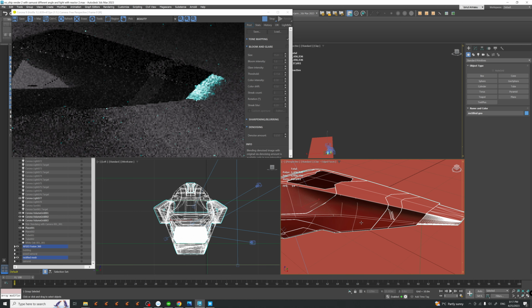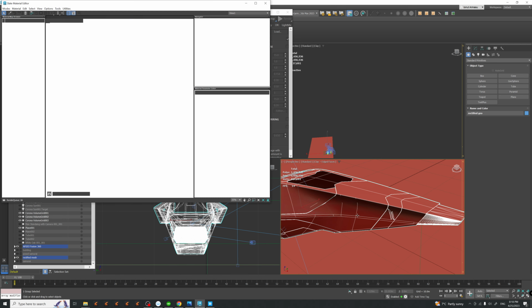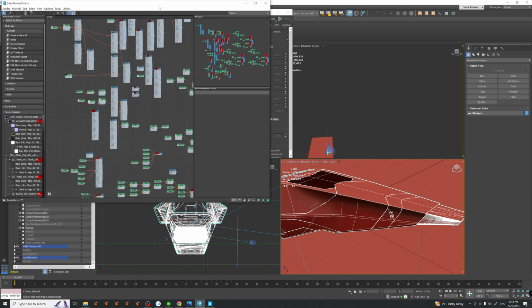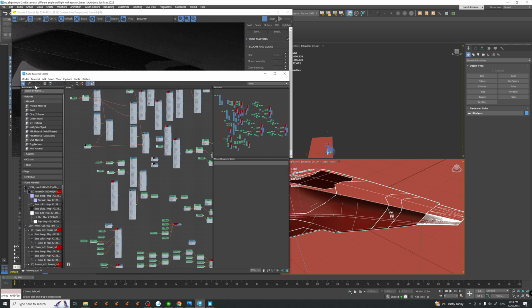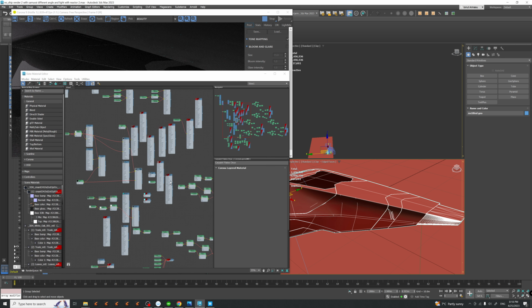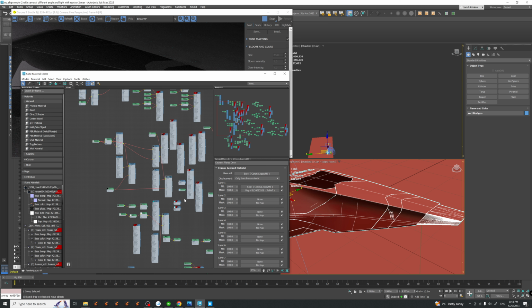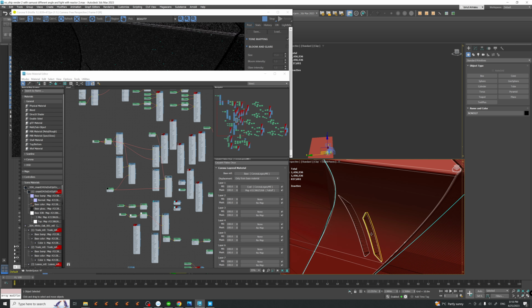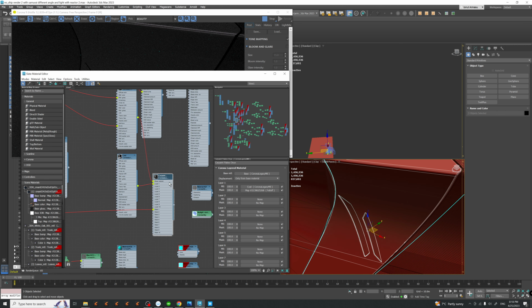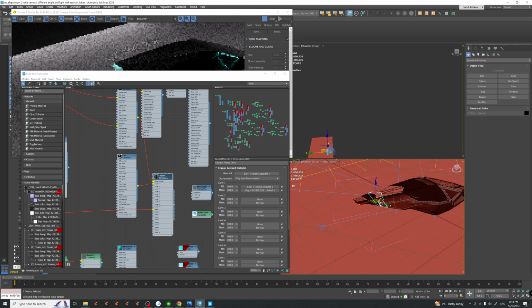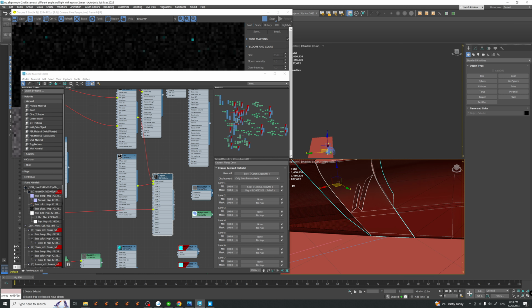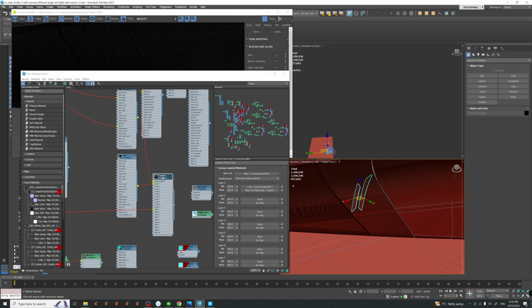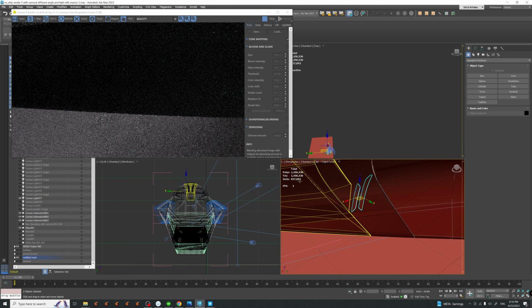I do have some materials in here that I want to adjust and that I don't like. So I press M, and let me see, where do I have the material? I did try quite some stuff around. So I go to the group, open it so that I have access to these elements so that I can assign the material. This is just a simple material that comes with Corona, the car paint shader, that I want to assign so that I don't have different materials.